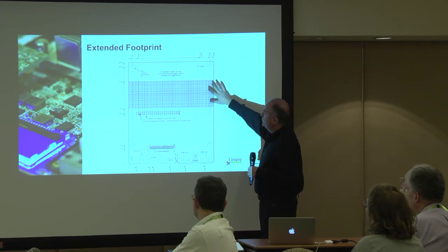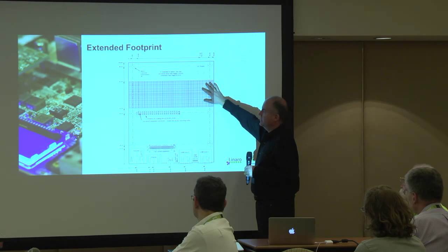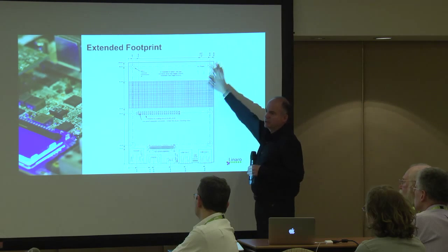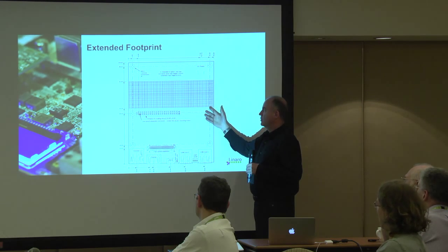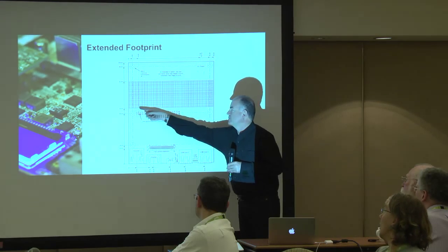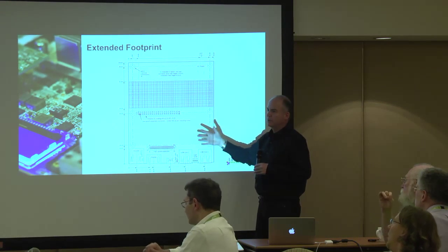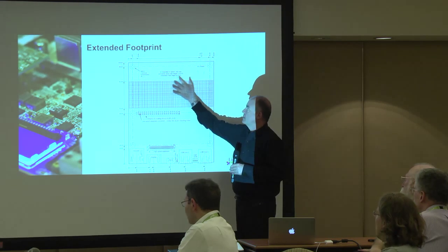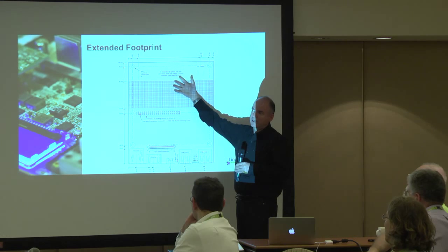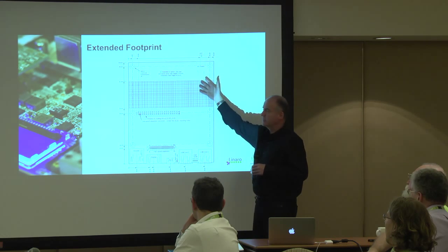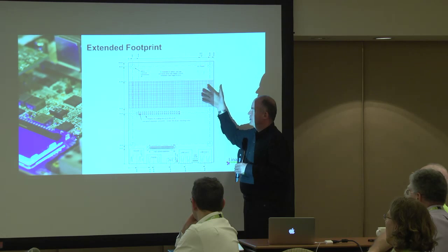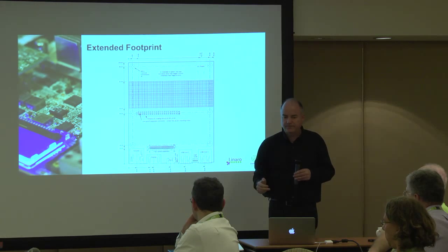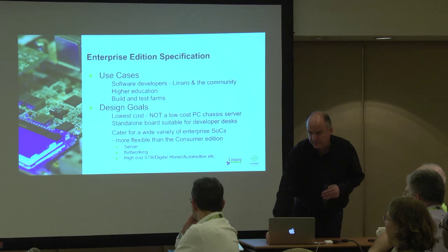So there are 2 versions of this extension. One is to keep everything low profile. And the reason for that is if you've got a big module, like a display module that covers the whole thing. The other option is you have to keep to the height restrictions here, allowing you to put compatible small format boards on. And then you can put higher components here if you want, like RJ45s or double stacked USBs. But in that case, you will not be able to fit any module that obviously extends this way. All right? Up to the designer.